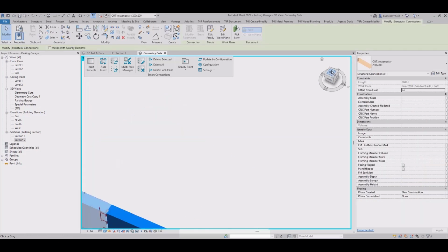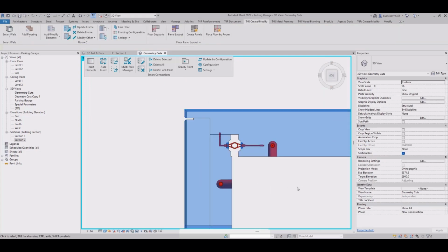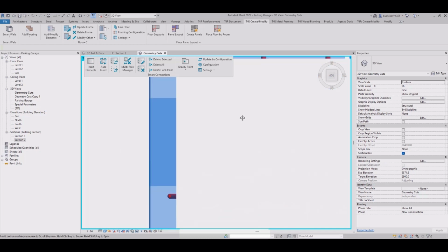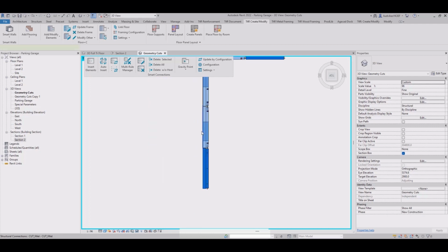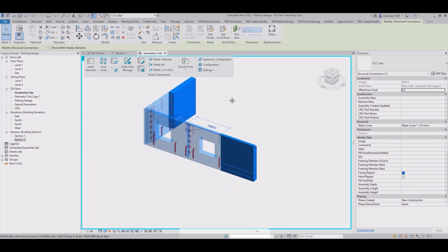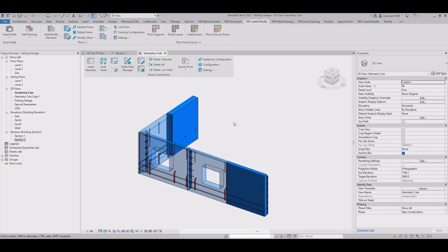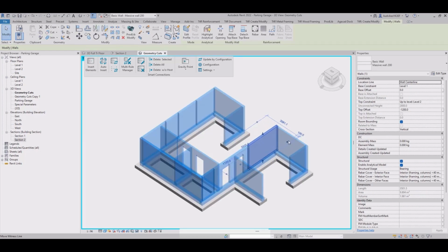So I have the precise volume and geometry for these walls. Also, I have loops added, and these loops can be any size, and we can have any size of our grout tubes, etc. The important thing is that I used a rule that identified the corner and added certain families that I wanted to have in that corner connection.